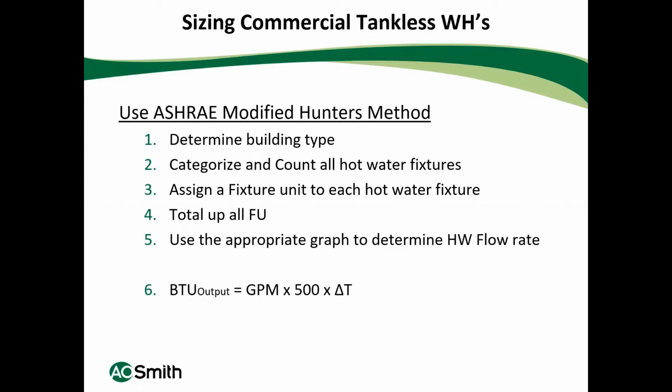Our commercial tankless units are 95% efficient. So whatever BTU output I get, I would divide by 0.95 to get my BTU input. We also have some tankless units that are 82% efficient. So we would divide the BTU output by 0.82.